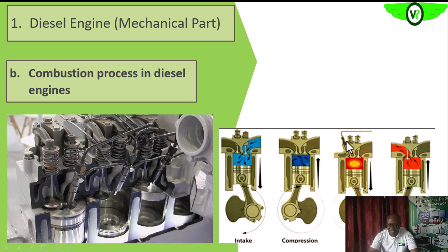Then at that instance, the injector nozzle, the fuel nozzle, will inject diesel fuel into the chamber. Remember that the compression force on the air has already heated up the air, in addition to the fact that this event may be happening when the engine is already hot. So as the fuel is injected into that compressed air, the air-fuel mixture will now ignite. That is what we are seeing here. And so it will now combust. That combustion product has very high energy.